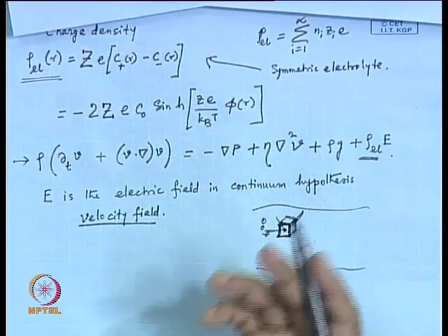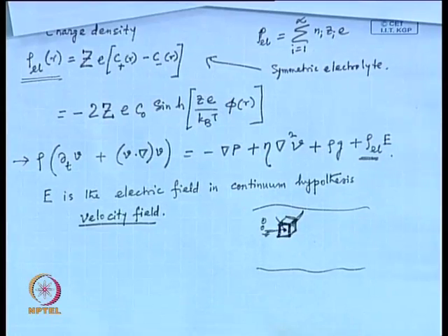In the first class itself we discussed this functionality, when you plot the density, or any function, against the probe volume. As you increase the probe volume, if you get the probe volume too small, then you get atomic fluctuations affecting the measurements, and if the probe volume is too big, then the macroscopic mechanism itself leads to a fluctuation. So, your probe volume has to be within certain limits.